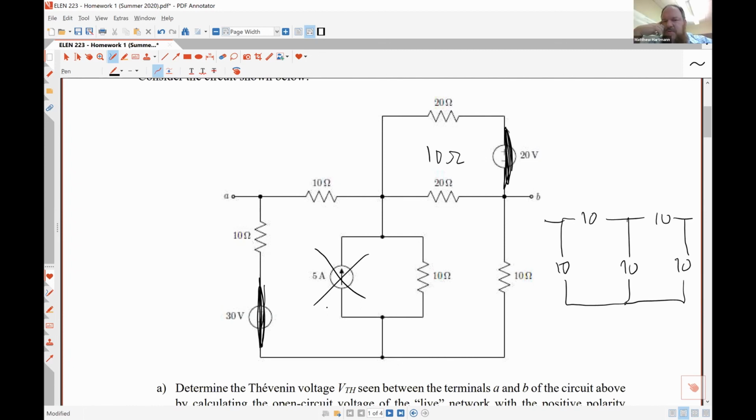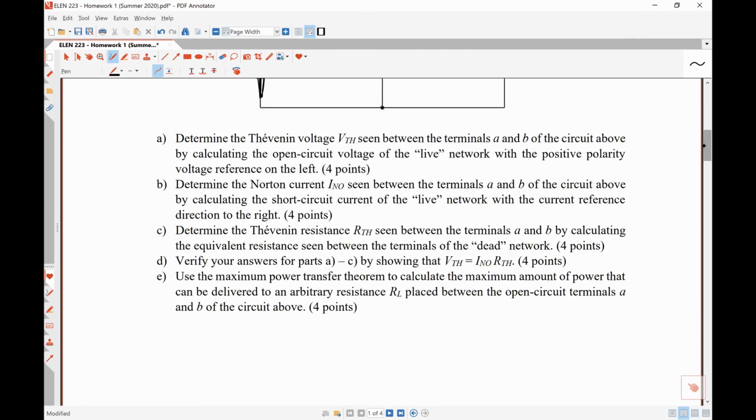The issue that we're running into there is that this 10 ohm resistor on the left-hand side isn't in series or in parallel with anything. Like you would have to use a delta Y transformation. A delta Y transformation. Yeah, which you obviously don't know how to do, so that is okay. I can post some notes on that. Let's see. Yeah, because when I was working this out, this would have only worked if only one of the 10 was gone.